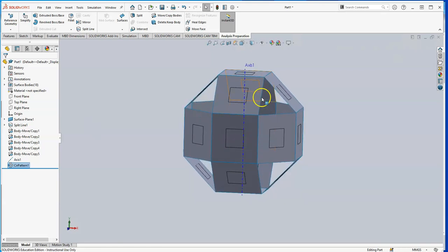And what I also need to do is then fill in these triangular faces here. So if I set this up correctly with correct dimensions, then I just need to create sketches on these planes where these triangles are, and then create faces on them. I need to create a plane, say in here, in this triangle.